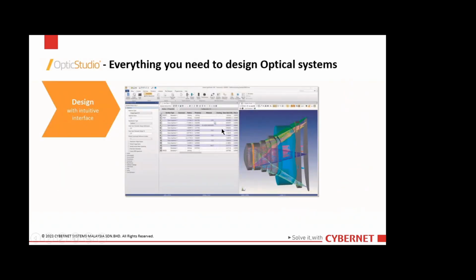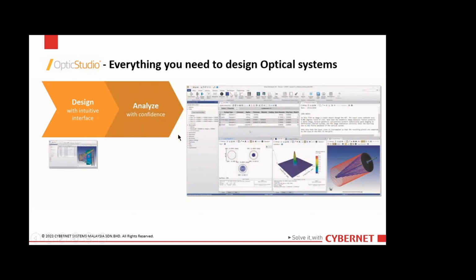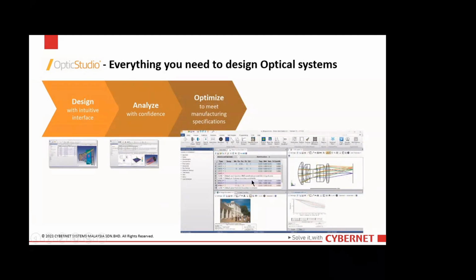So here is the workflow. We start with design. We may have a lens set with the radius, the surface type, and the thickness, which we enter in the Lens Data Editor. After that, we use the analysis tools like just now, so we can analyze before we optimize. Then we can optimize the design by using the wizard, just keying in the requirement or design specification inside the tool.